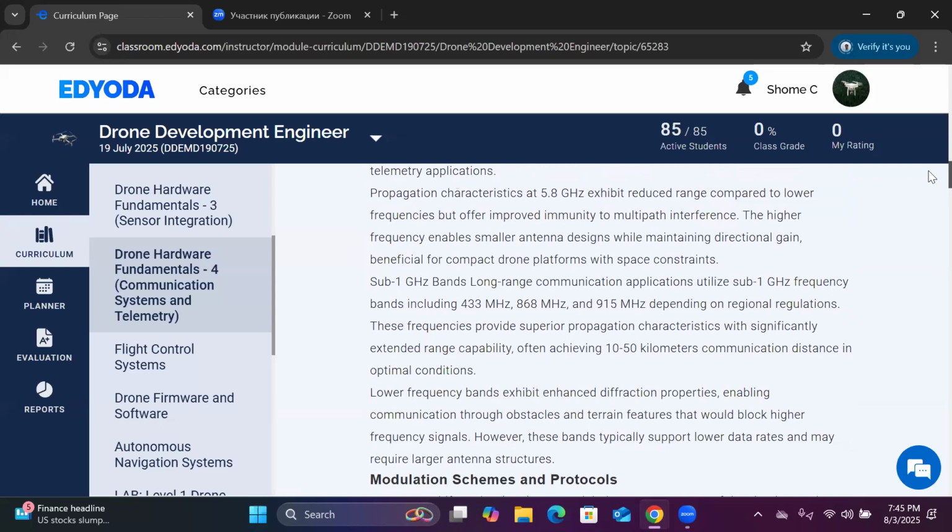And on the GCS side, basically the communication box side, there are two types of entities. One is the HHRBT and the other is called the communication box. The HHRBT are connected with different kinds of radiating antennas, either omnidirectional or directional. And the communication box, which is bigger in size, usually encompasses a patch antenna or a grid antenna or a phased array antenna.